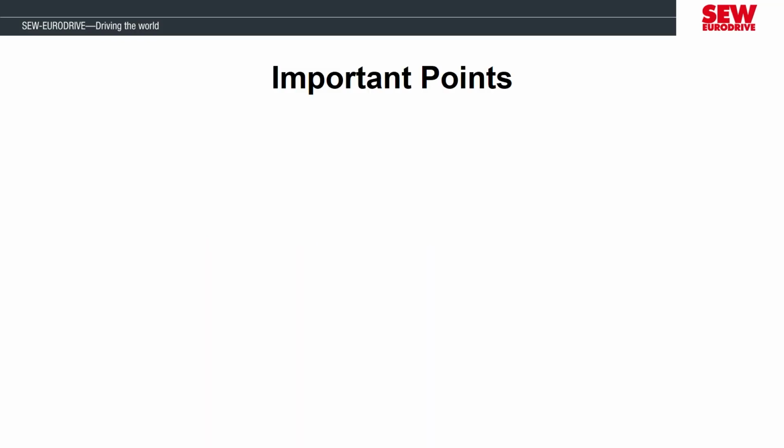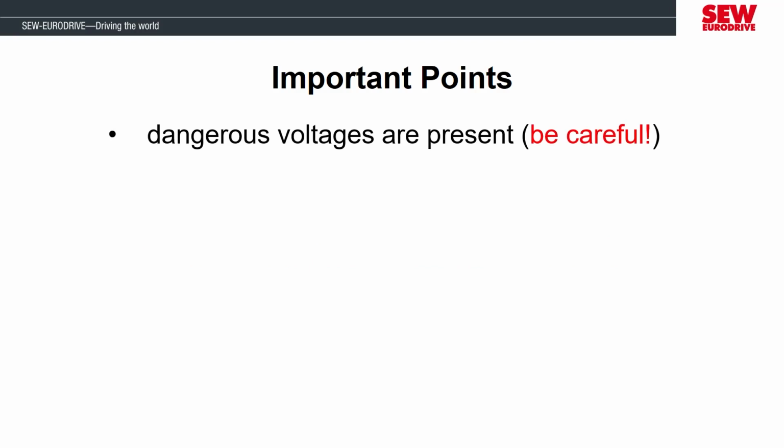If you're using a MOVIDRIVE through these exercises, let me remind you of some important points. The MOVIDRIVE is connected to high voltage and it can maintain a charge for several minutes even after the power is switched off. Don't touch any wiring, terminals, or the end of power supply plug connectors because you could be shocked. Always use metering equipment to check for the absence of voltage before you touch any of the encoder or high voltage cabling.